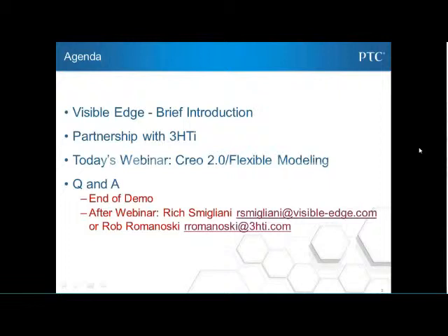Now I got another question regarding issues with modifying family table items. So these are features that you can add to a family table. Sometimes, again, the only issue might be if you're making, say, a modify analytic where I gave something a dimension like the hole or some feature. A lot of the issues I've seen are really regeneration issues. So if you put in something and you change the value, it changes to a dimension that causes the model to fail.